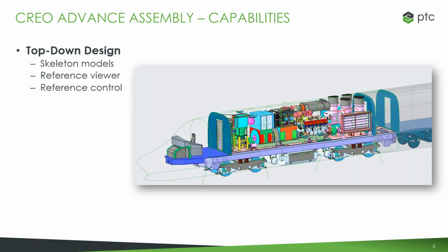Because you're able to define best practices and manage and limit the assembly component references, what are you going to attach your parts to, right? It's going to be those key pieces of geometry. We need to be logical about what everything references so you can keep your assemblies flexible over time. At the end, it's very easy to update and make complicated changes because everything's referencing only a few pieces of geometry, and you have the viewer to understand what's going to change where.